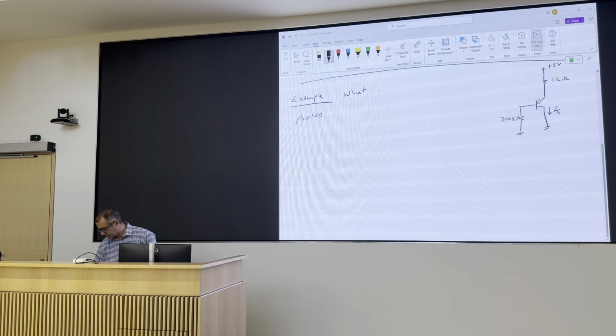So usually you take into account the early effect for small signals, when you're making amplifiers, all that stuff. If you're making amplifiers with off-the-shelf transistors, you don't care. It doesn't affect you. The equivalent resistors that you put in your model are really not going to improve your accuracy very much. Okay, that's that. Any questions? So early effect, this is as much as we need to know about it. Just know that the current doesn't stay constant, but you're going to have a hard time measuring it.